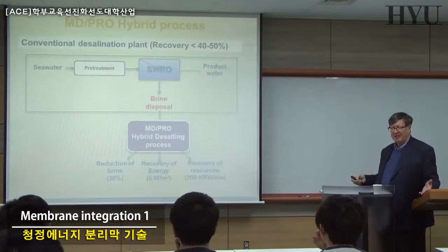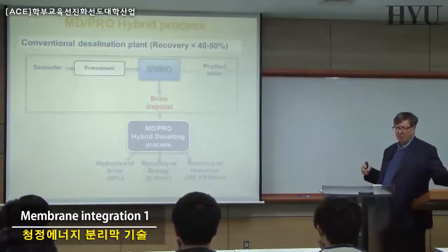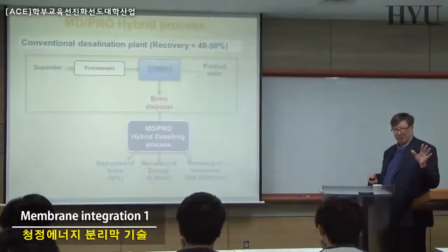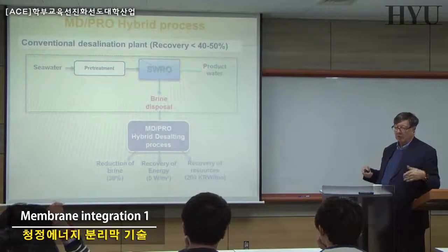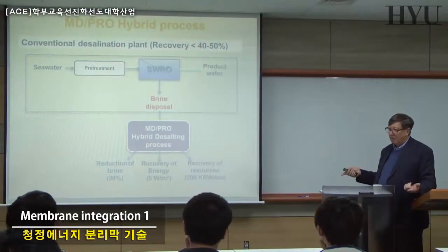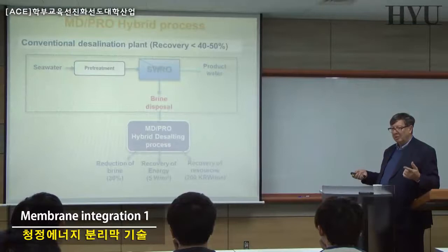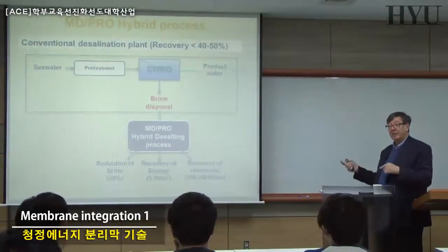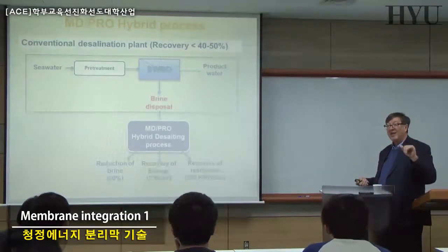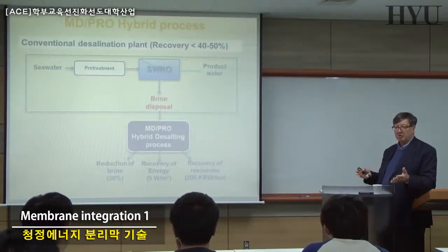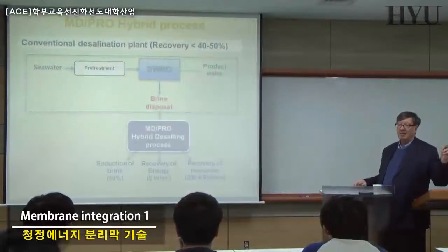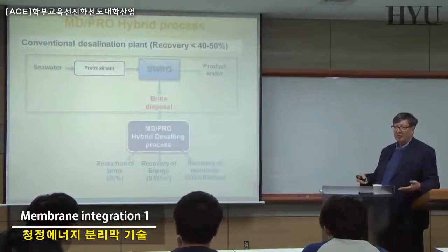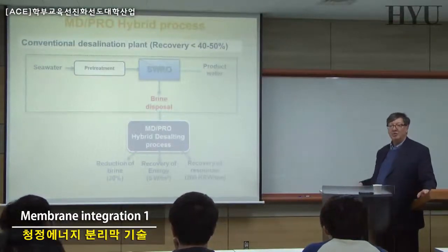The brine from desalination is 1.5 roughly. No, seawater is 0.5. In traditional RO, where you can have a recovery factor of 50%, the brine is between 1.4, 1.5. Power density is still low if you are working with this concentration. If you combine MD and PRO, this 1.5 molarity can be 4, 5, 6. You approach precipitation. And in this case, you can arrive at 20 watts per square meter. And with 20 watts per square meter, if really working for years, you can cancel nuclear energy, for example.